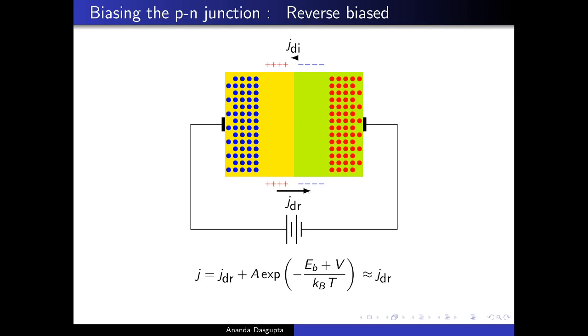And you have to also remember one very important thing, which is this minority carrier current actually grows with temperature, and that's going to be critically important in some applications, as well as a source of major annoyance in some devices.